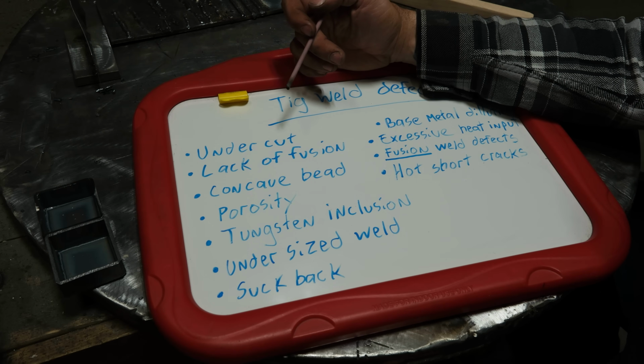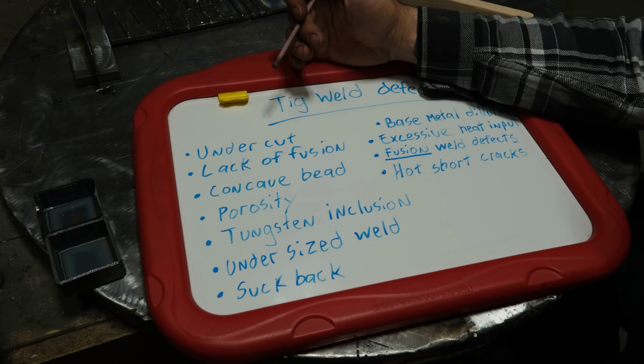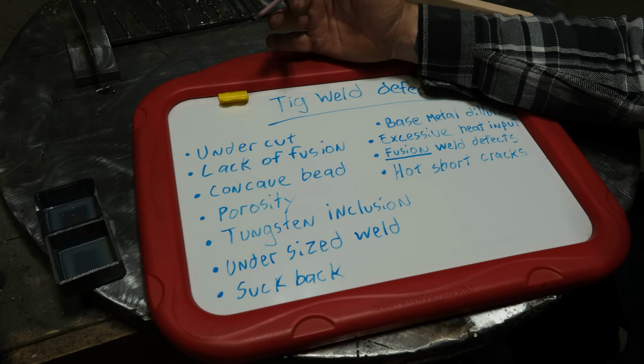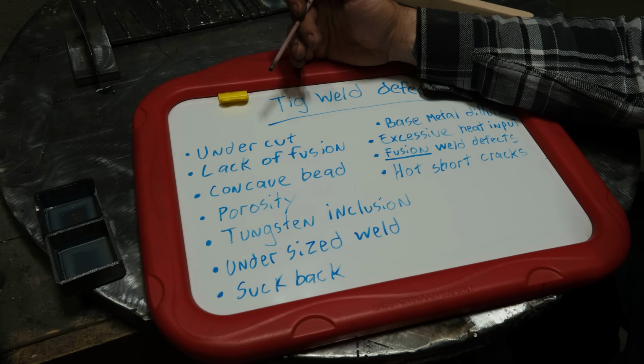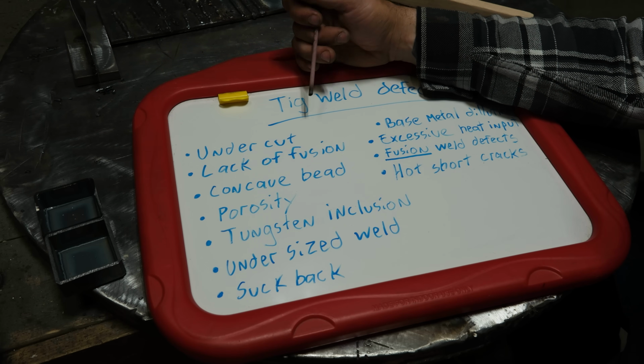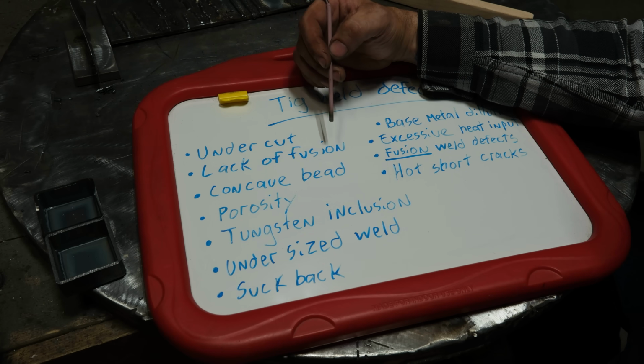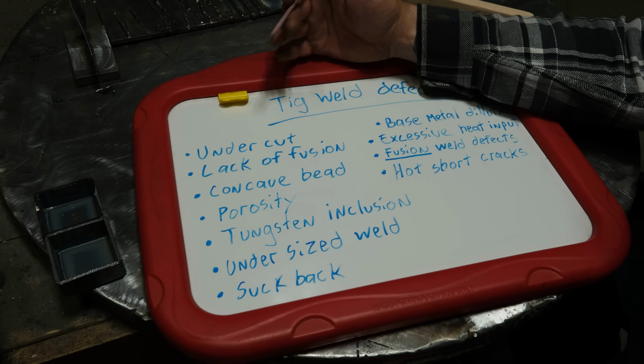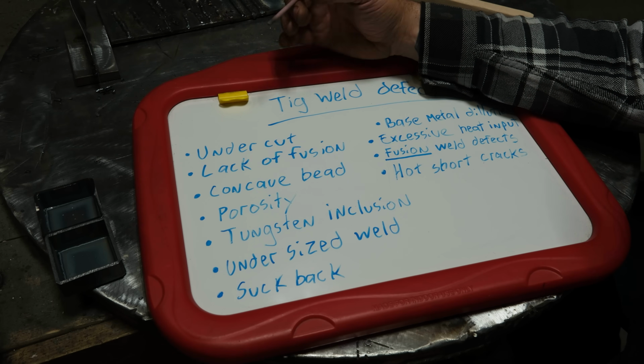If you're going to weld 1/4 inch or some thicker steel, maybe you should do a test joint the way that you think is correct with your TIG welder, and then cut and etch it and look at what the penetration is. If you have a lack of penetration or a lack of fusion, then guess what? You need to change something. More than likely tighter arc, slower travel speed, etc.